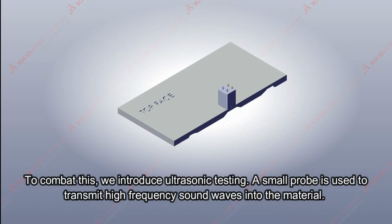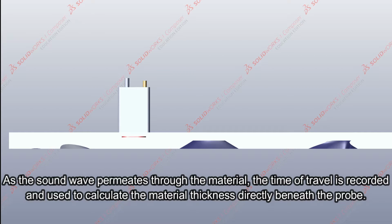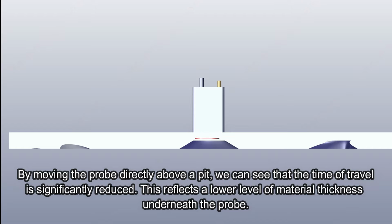A small probe is used to transmit high-frequency sound waves into the material. As the sound wave permeates through the material, the time of travel is recorded and used to calculate the material thickness directly beneath the probe. By moving the probe directly above a pit, we can see that the time of travel is significantly reduced. This reflects a lower level of material thickness underneath the probe.